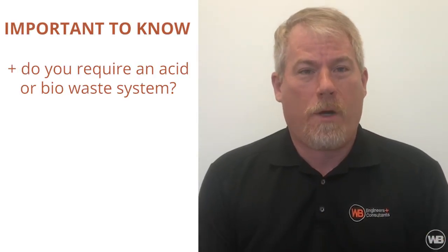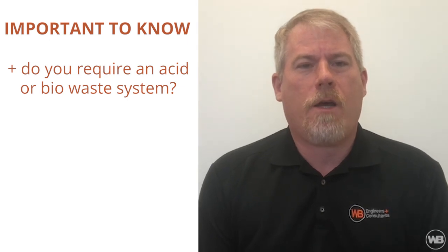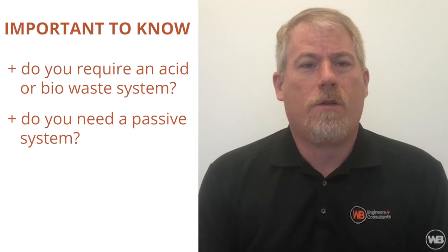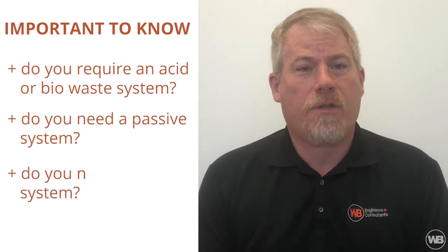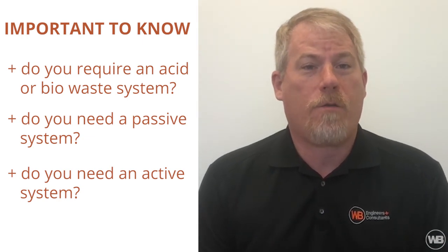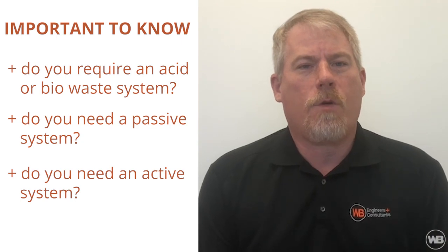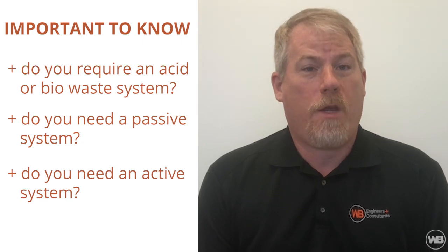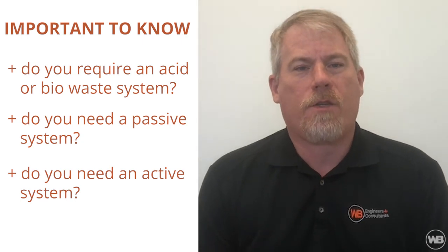So making sure that you have the right people in the right place to design and analyze these systems is real important. In summary, it's important to know whether you require an acid waste or bio-waste system, if you need to have a passive system for mild chemical use, if you need to have an active system, you need to then determine, is that active system for both biologics or lab waste, or both? Will it be a chemical kill system or neutralization system, or will it be a heat-based system to kill live biologics.